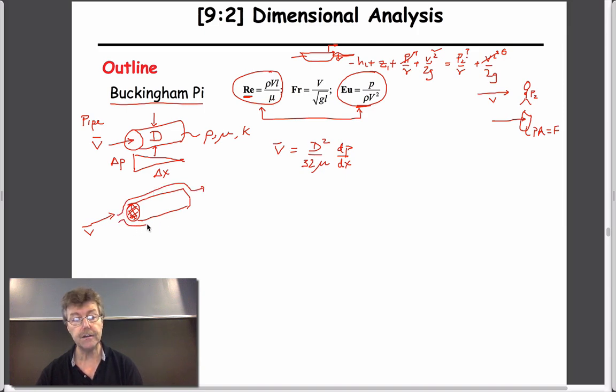A bit like our cylinder, but now it's a long cylinder, a different aspect of it. And actually, the same kinds of behaviors you'd expect. There'd be a pressure change between here and the backside. In this particular case, the pressure difference is really driving the flow along here, and it's driving it against shear stresses that are applied on the inside of this pipe.